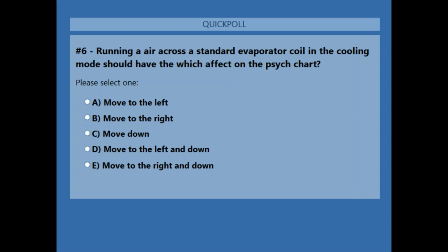However, if your humidifier involves electric coils with electrolysis, you may be better off having the cooler water, because the cooler water would have more minerals in it that would do a better job conducting electricity. Whereas with warm water, many of the minerals are precipitated out, so it is harder to use that with an electric humidifier. So it just depends on what you're doing there.